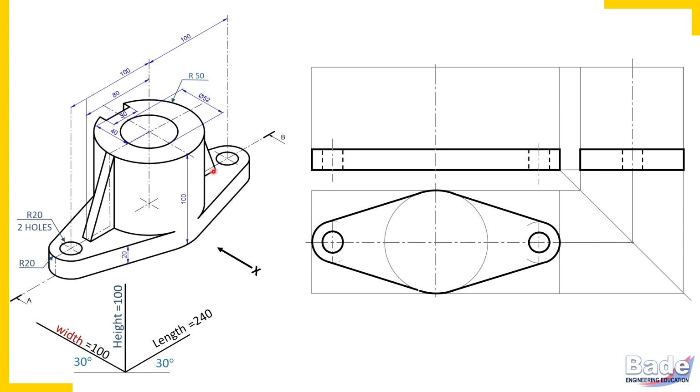Okay, now let's proceed for the cylinder. Two concentric circles because it's a hollow cylinder. Just check the corresponding radius and draw these two concentric circles. Cylinders appear as rectangles in other views. In one view a circle, remaining two views rectangle. Simple. It's a vertical cylinder, therefore in the top view it's a circle, remaining two views rectangle. So draw end projectors and complete the cylinder. Height of the cylinder, from the base it is given, 100 millimeters. So of course up to the top.